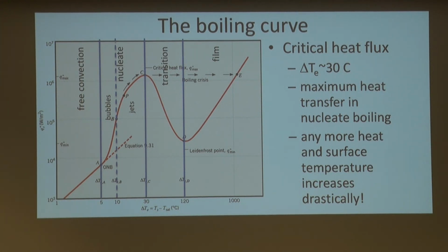We've been looking at this curve as saying, oh, if I increase my excess temperature, right? And the curve makes sense to you. But in reality, you seldom do that. What you typically increase is the amount of heat you put into it. And this curve actually was first developed, and I'll show you the type of experiment they did, by electrically heating a wire, right? So you know how much heat you put, and you can put more or less heat.